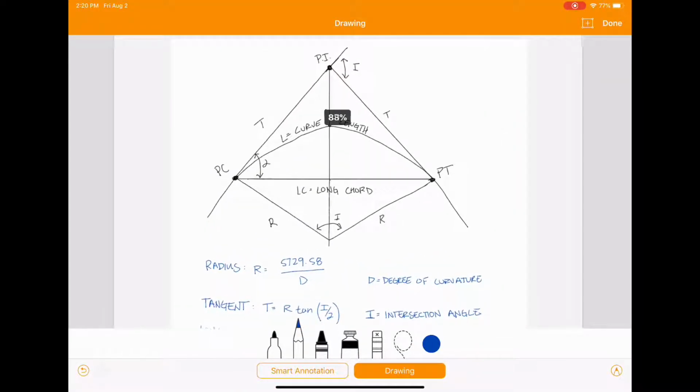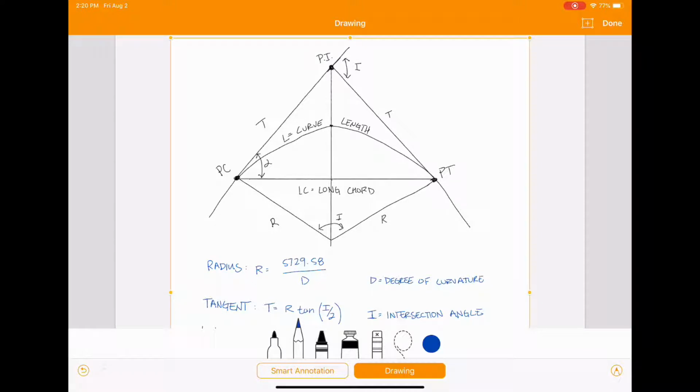that you will have your horizontal curve, which is this here. That's your curve. And in order to set it up with your surveying equipment, you're going to need to know a couple of these different points here. So this is the starting point, which we call PC. It's the ending point of your curve, which we call PT. And then if you draw tangent lines from the curve through those points, they intersect at this PI station.